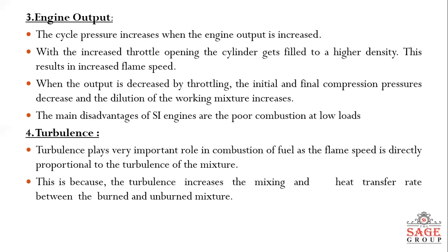Next factor is turbulence. The turbulence plays a very important role in the combustion of fuel, as the flame speed is directly proportional to the turbulence of mixture. This is because the turbulence increases the mixing and heat transfer rate between the burnt and unburnt mixture.